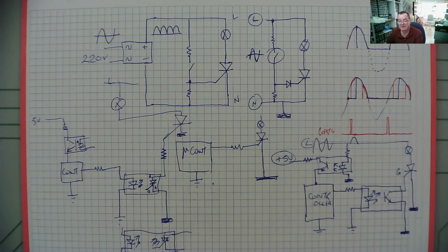If this video is really going to be all you need to know about thyristors to fix stuff, then we just need to talk about what goes wrong with them. Normally speaking, if a thyristor fails, it goes short circuit. They may go open circuit, but short is what normally happens with them.